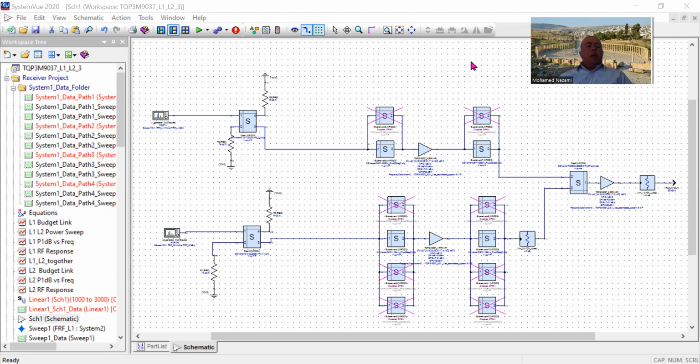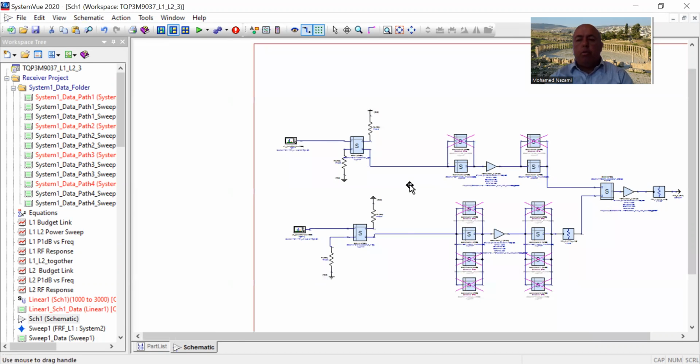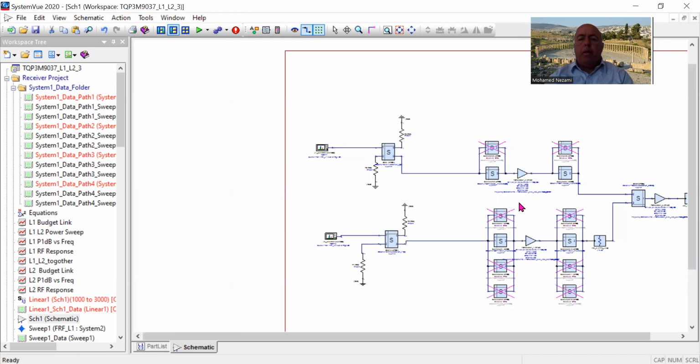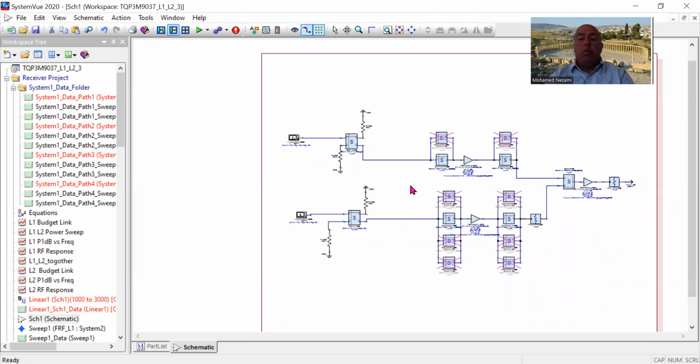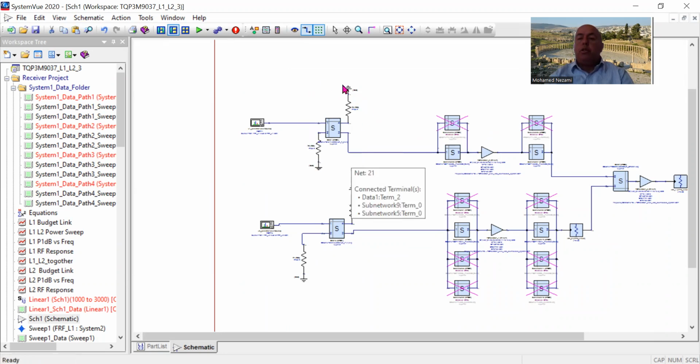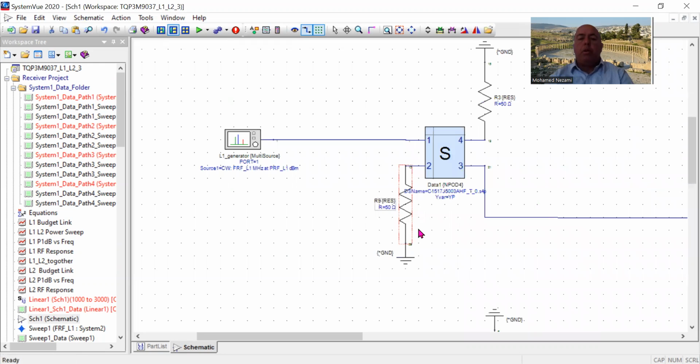guidance, and whatever. So what you're looking at here today, I'm going to go through the design of a dual band L1, L2 designated bands low noise amplifier. We're going to start out with an antenna interface 90-degree hybrid that basically combines. Right now I've got one terminated input, but normally this input is connected to one polarity, and this one is connected to another polarity of the antenna, as I will show in a minute.